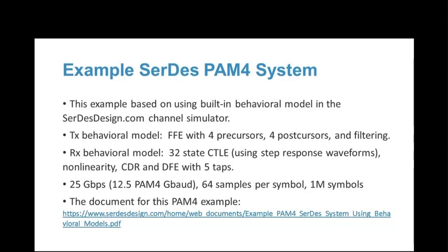I was using the PAM4 data format with 25 gigabits per second. That's 12.5 PAM4 gigabaud, 64 samples per bit, and 1 million symbols. The transmit behavioral models are listed here, and the receive behavioral models are listed here as well.